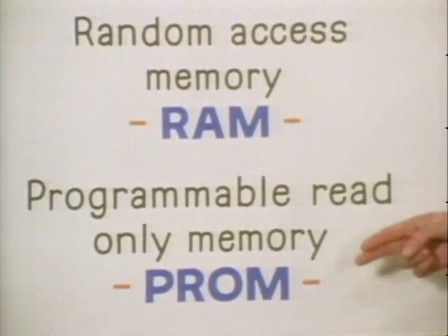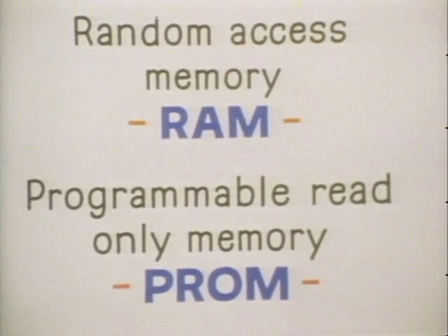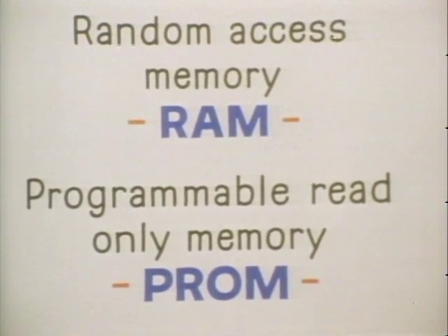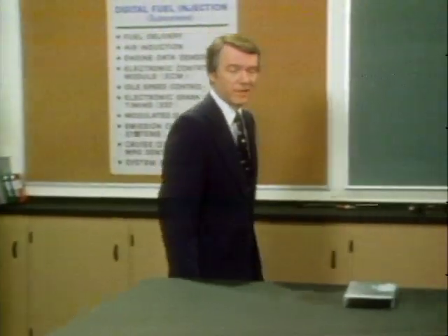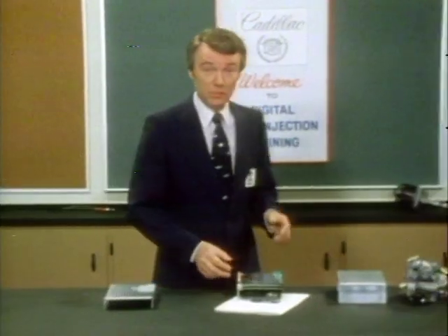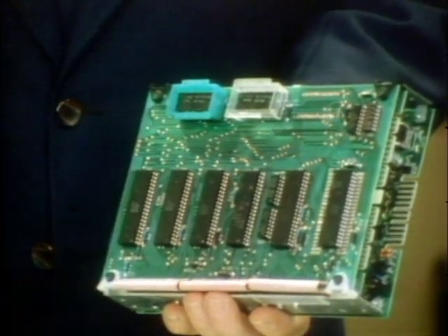Programmable read-only memory, PROM, contains specific engine calibration data for each emission system and transmission. This memory device is programmed by Cadillac Engineering, and its information is retained permanently. There are two serviceable PROMs in the ECM.